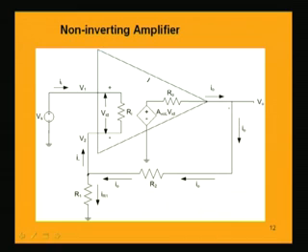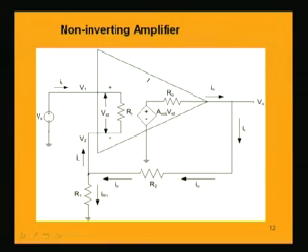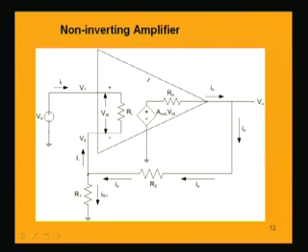Now, here we will be finding out the output voltage. So, what is the output voltage for this non-inverting amplifier? If we look into this circuit, V0, this voltage, is nothing but AVOL VID minus the drop in the resistance R0, because the output resistance R0 is there, it is not 0. So, the voltage which is available at this source is AVOL VID, VID being the difference in the voltage. So, we are following the op amp principle that the difference voltage is amplified by the open loop gain, AVOL VID, minus this drop I0 R0, that is V0.